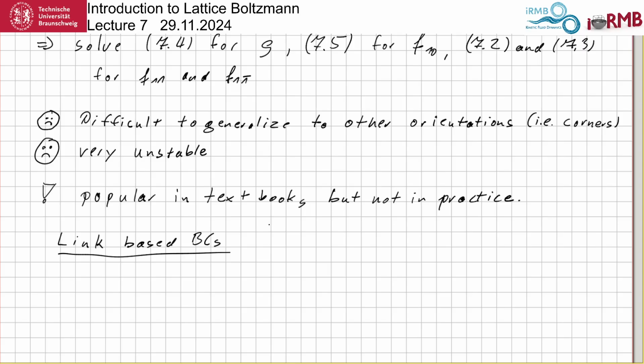Now bashing the past, we were talking that to people in the past it appeared to be a very natural thing to put boundaries on the nodes. Now, when you follow our analysis, which I would claim is a little bit more modern than from the 90s, nowadays we are using this in-between time step thing a lot. So we notice we are actually solving the equation not for the pre-collision part, as is done in the Zou-He boundary condition, and not for the post-collision part, but for the average between before and after collision.